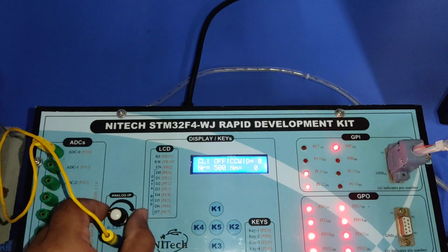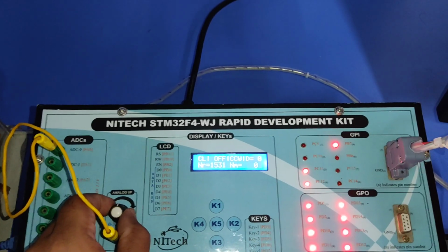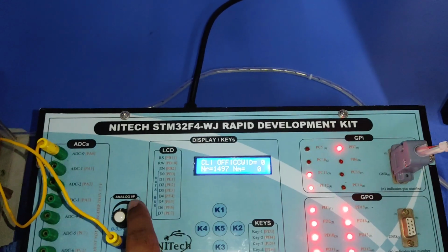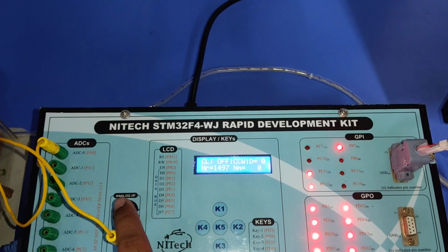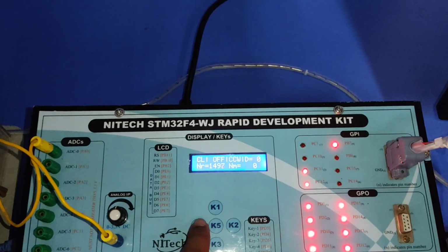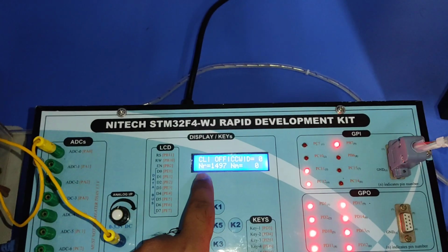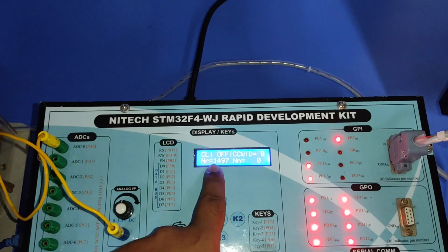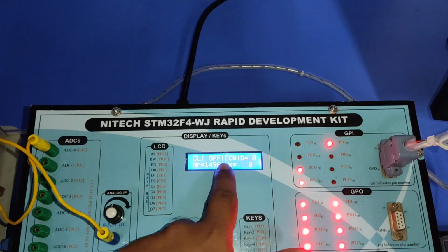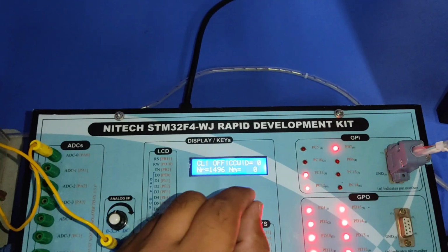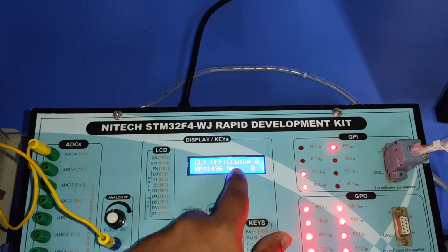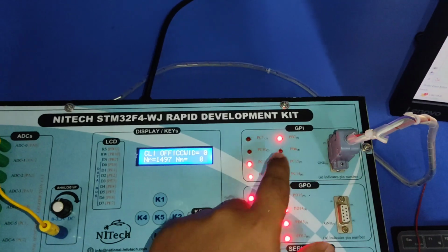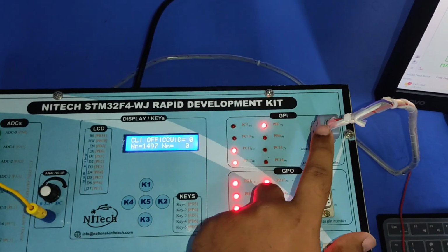So if you want to change your speed from 500 to 1500 RPM, then you can set this reference speed by using this analog port. Then you can apply this speed to the controller. By pressing this K4 button you can apply your reference speed to the controller, and it will take some milliseconds to get your actual speed. And the duty you get according to your PI, and here you can connect the encoder input.